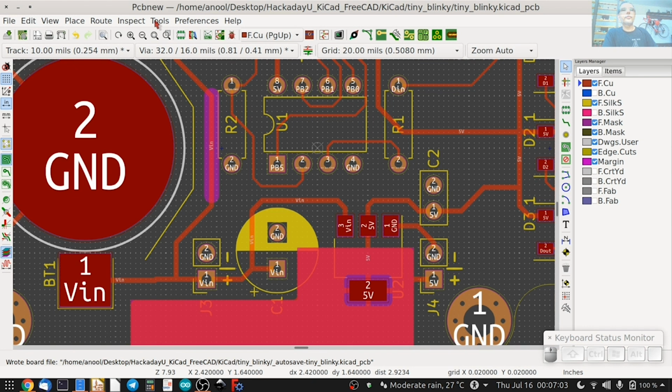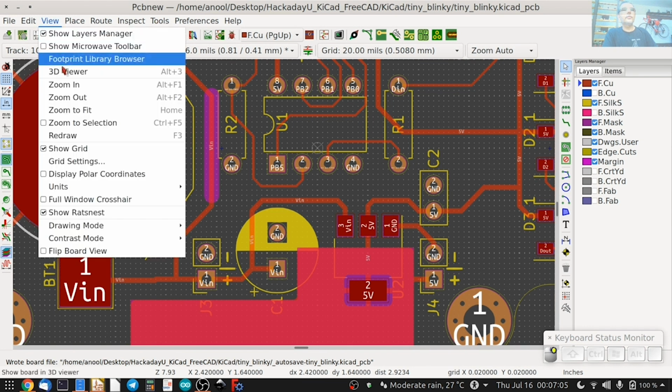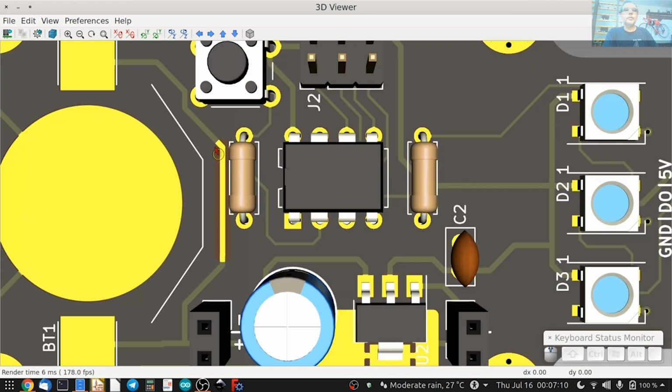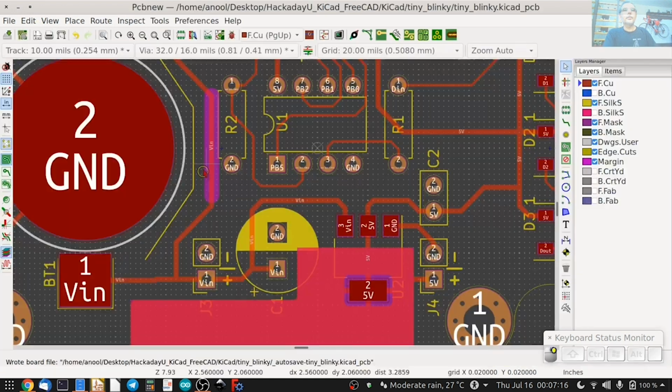And what it does is it makes sure that the solder mask is removed from this portion of the track. So if we look at the 3D view, you can see the result of this, which is over here. You can see this part of the track has been uncovered now. So that's solder mask expander. Let me delete that as well.